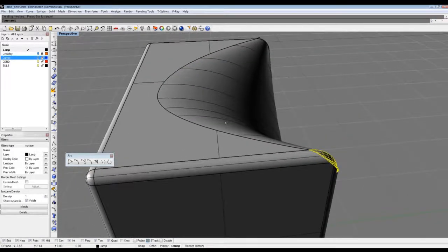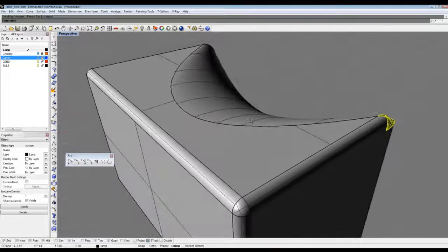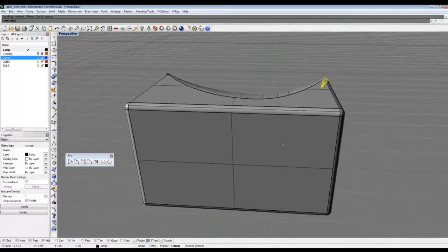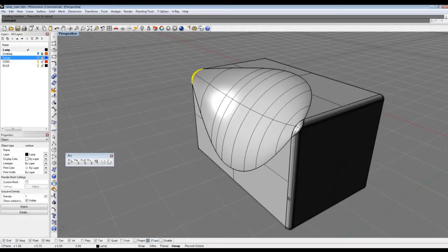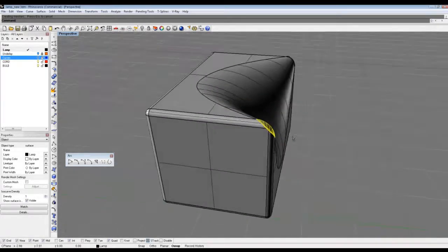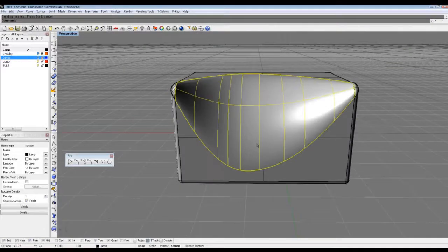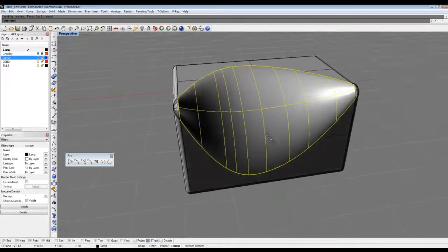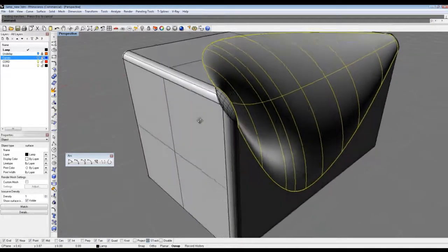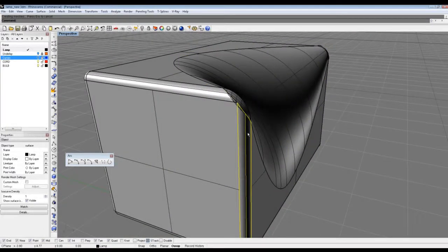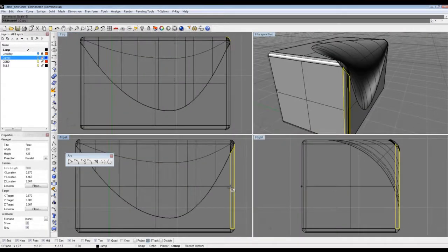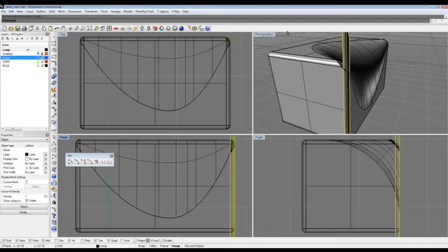Rhino is great for surfacing, not the best for filleting, in my opinion. I think SolidWorks does a little bit better because it'll just not do a fillet if it won't work. But otherwise I would say experimentation is definitely key. If you get an issue where oftentimes your result will look something like this, where your fillet will be way out here, and it's like, well, what the heck?